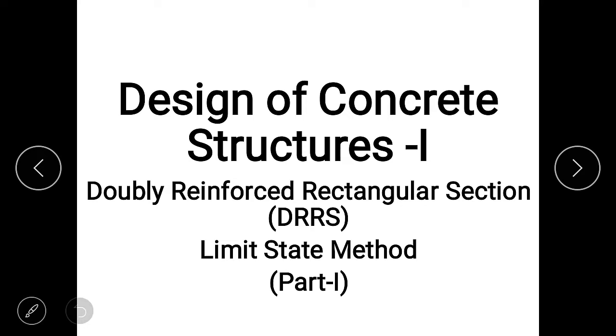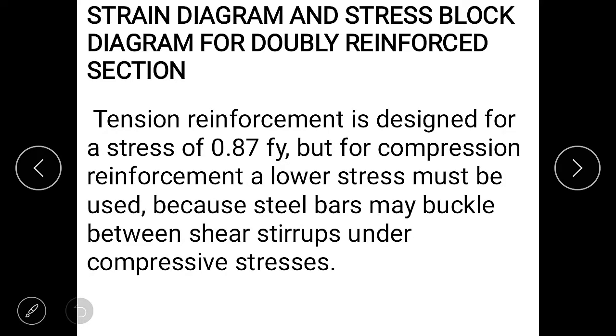What is a doubly reinforced section? We provide steel in the compression and tension zones also. It is called a doubly reinforced section. Next, the stress-strain diagram and stress block diagram for a doubly reinforced section. We have to study how to design a doubly reinforced section.